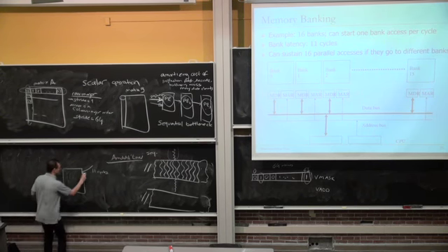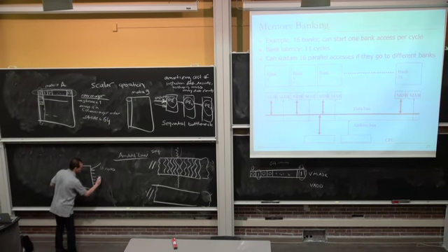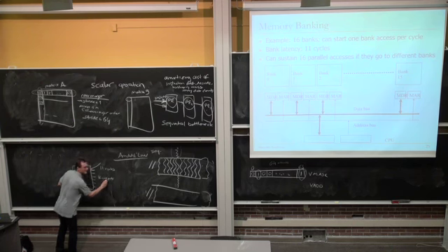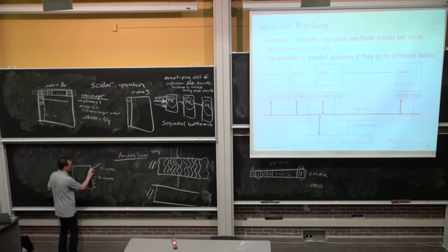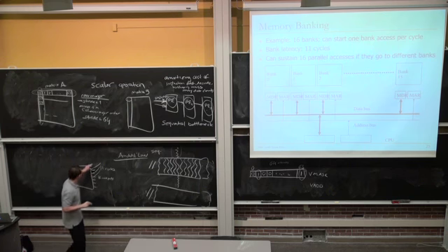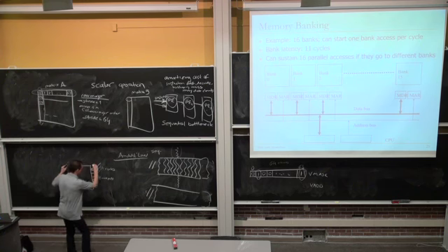What you can do is you can have 16 ports to this memory, 16 read ports, if you will. But that's expensive, right? Does that make sense? You can start the first access in the first cycle, the next access in the next cycle in the next port, the next access in the next cycle in the next port. So you can actually sustain 16 accesses at any given time. Actually, you really need to sustain 11 accesses, right? Because you can use the next port at the end of the 11th cycle. Well, this is an expensive way of building a memory that you can access in parallel for different elements. This is called multiporting.